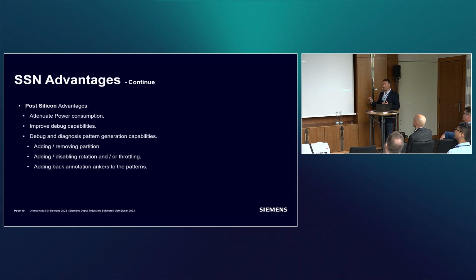That will help us with the power consumption, because previously we should have kept the EDT low power shift feature, since sometimes you'll get IR drops if you shift or scan enable the entire design, or you need to change between power domains. You'll have different shift clocks. That's also IO consuming. We don't want that. So the power consumption is really attenuated now.